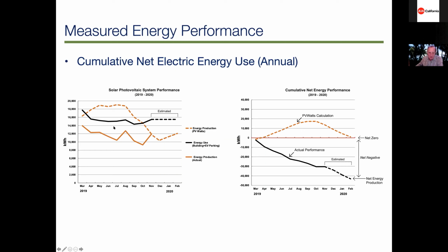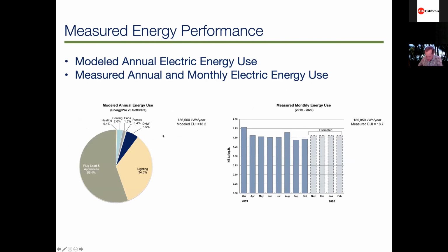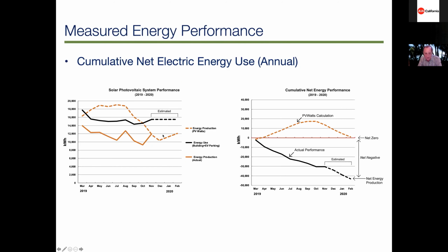And what was happening, just to cut to the chase, was that an inverter on one array of panels had failed right at the start, and they didn't know it. And it was operating without the full array. And there was another problem in that this part of LA gets a lot of air pollution, a lot of dust, and the panels were getting covered with dust. And so they were operating below what they potentially could.